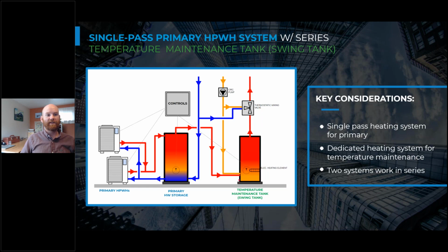So we want to appropriately size the volume of the storage tank to be large enough that we can swing the temperature in this tank from 140 down to 125 during our low use period. And then overheated water comes back in and starts to charge this storage tank again once we have use.